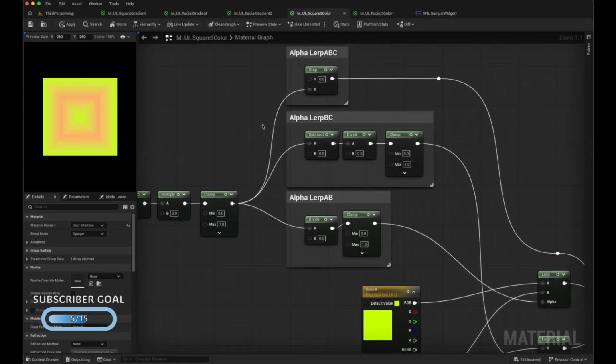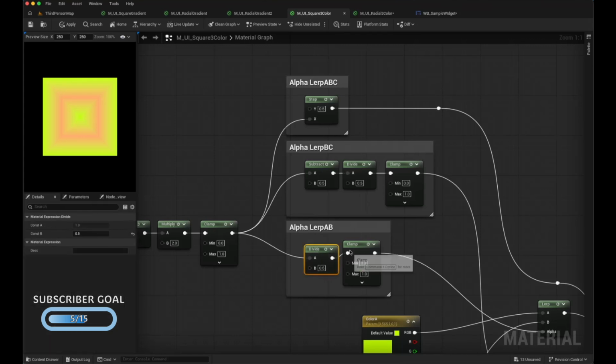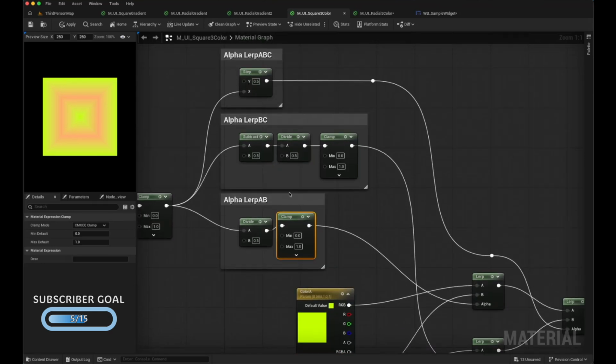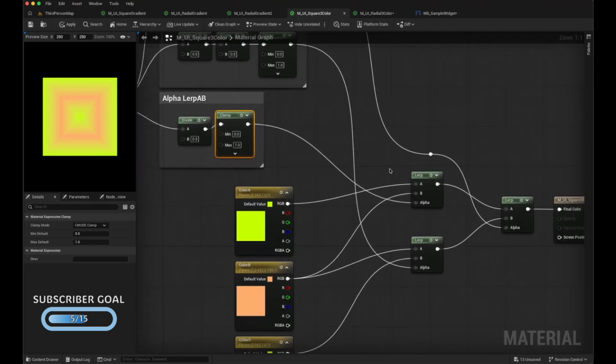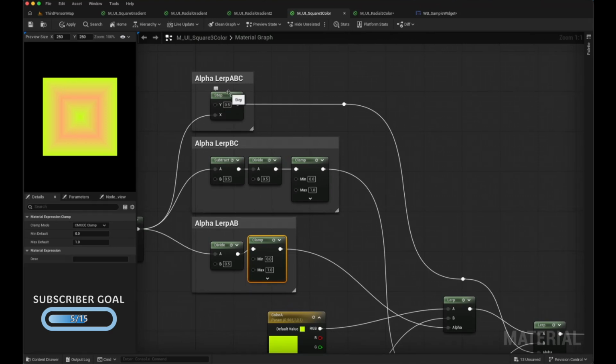So from our clamp node, we want to get 3 alpha values. We will get our alpha value for lerp AB by dividing it by 0.5 and clamp. This will be our alpha value for lerp AB. For our lerp BC, we will subtract 0.5, we will divide by 0.5 and then clamp it. This is our alpha value for lerp BC. For lerp ABC, we are just using a step function. Anything below 0.5 will be lerp AB and anything above 0.5 will be lerp BC. And that is our 3 color square gradient.